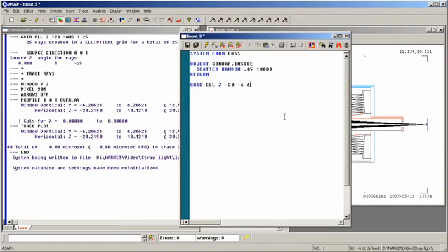So it's -6 to 6 in the x direction, -6 to 6 in the y direction. For simplicity, we'll use an in-plane grid of rays. We'll say 25 rays in the x direction and 25 rays in the y direction. For direction of the rays, I'm going to say source, direction.